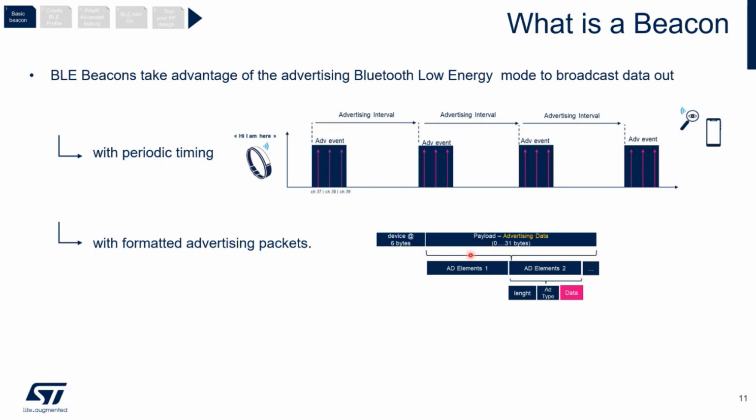And here the specification will tell you that you can push what you want over the air: the temperature, a name, whatever you want. The only thing you have to specify is that prior to each piece of data you are pushing, you have to prefix the data with an advertising type. Those advertising types are part of the specifications: local name, manufacturer data, service UUID data, okay?